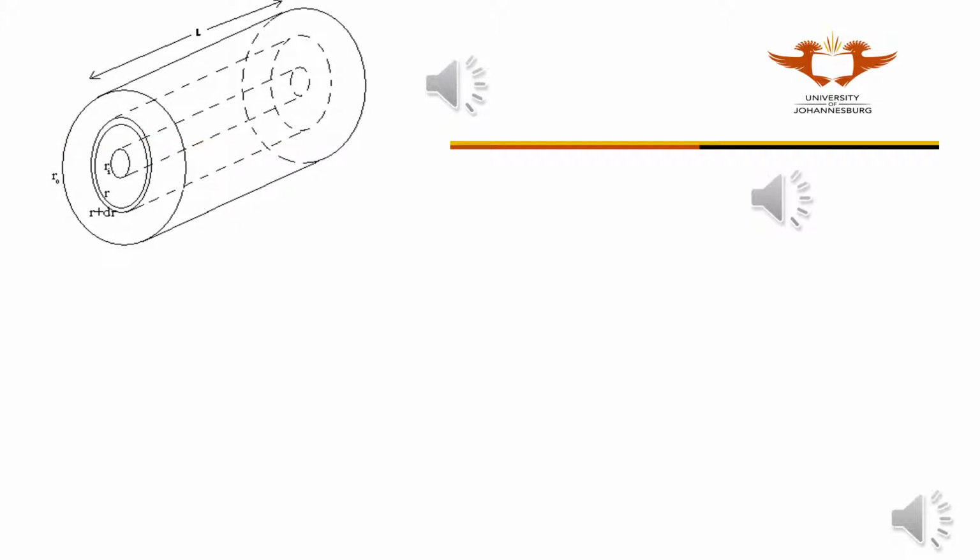You can apply Fourier's law to a thin sliver of cylinder, from where the radius is r, to r plus dr. The heat transfer area across this small increment remains 2 pi r L. Similar to the flat solid plane, you can now integrate Fourier's law from the inner radius, r_i, to the outer radius, r_o. This is from a heat source to a heat sink, if the heat flows outwards. Note that r has been moved to the left-hand side, the dr side, so that the variables are separated, as required in integration.